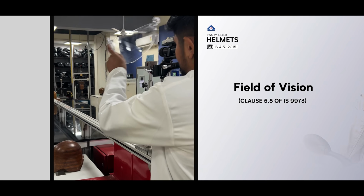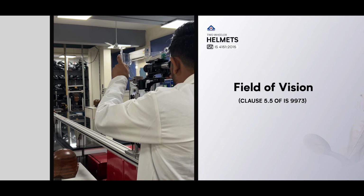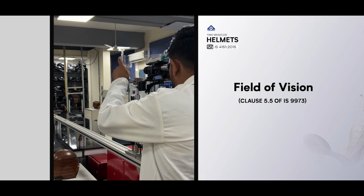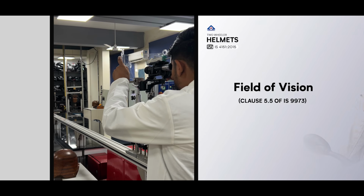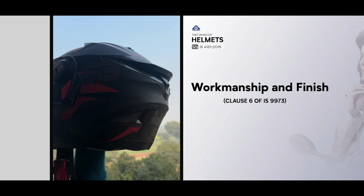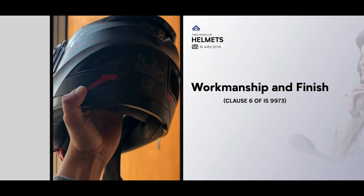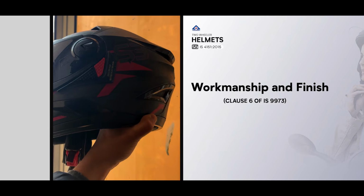The visor must provide a wide and unobstructed field of vision as defined in IS 4151. This ensures that the rider has adequate peripheral awareness. Each visor must be free from scratches, bubbles, and visual irregularities. Edges must be smooth, ensuring the visor is safe and visually clear.